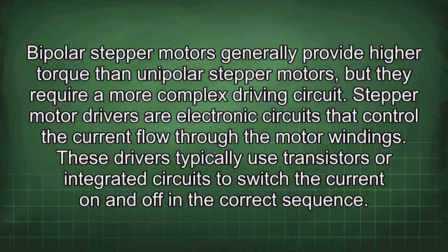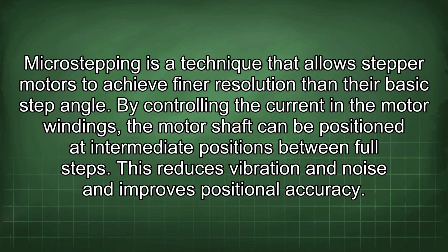These drivers typically use transistors or integrated circuits to switch the current on and off in the correct sequence. Microstepping is a technique that allows stepper motors to achieve finer resolution than their basic step angle. By controlling the current in the motor windings, the motor shaft can be positioned at intermediate positions between full steps. This reduces vibration and noise and improves positional accuracy.